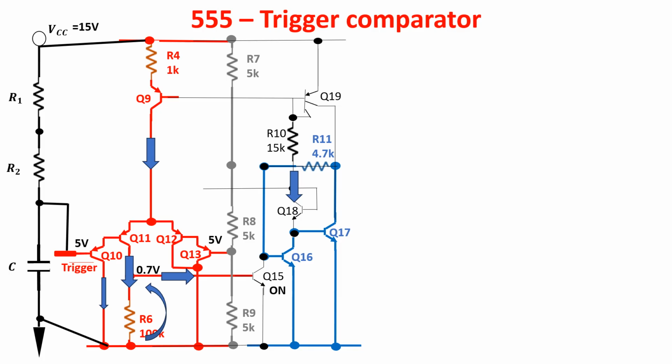However, according to the datasheet, in that moment the trigger needs between 0.5 microamps and 0.9 microamps as Darlington base current. So the discharge current flowing to ground has to be at least 0.9 microamps, and then the R2 resistor has to be less than 5 megaohms.